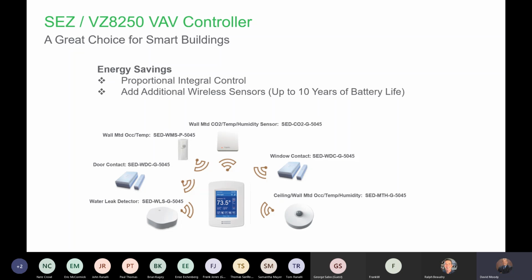So I point this out because this is where the beauty of the wireless ecosystem comes in. It allows you to solve some problems that typically exist in buildings, where I've mounted a temperature sensor to control the VAV box, but I've got 10 other people that want to have a say on that. Now you can do that all with one device, right? I'm sorry, Dave.